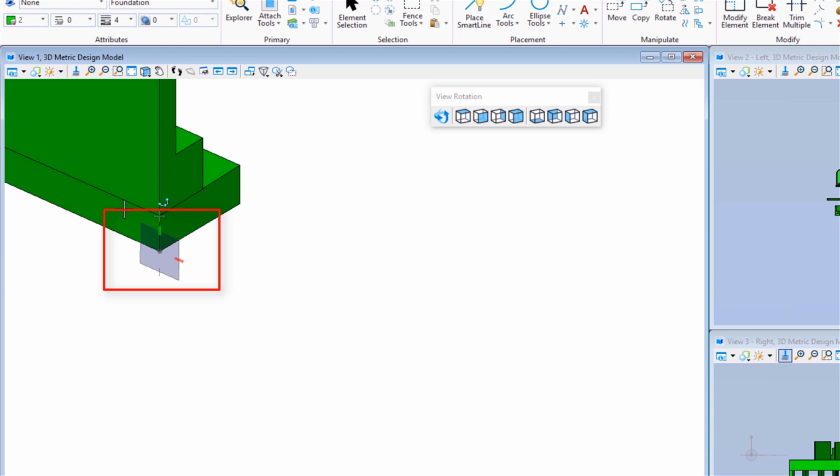You can see as I move it over the sides, the compass begins to change orientation based upon where on the solid I'm lining up with. So I'm going to move it along the edge so that it lines up along that edge. I'm going to do a data to accept it, and now my compass is rotated to be planar and lined up. Its x-axis is lined up with the edge of that slab.